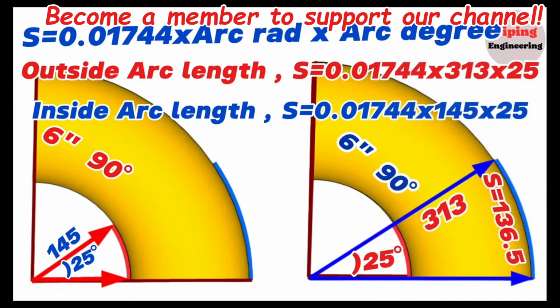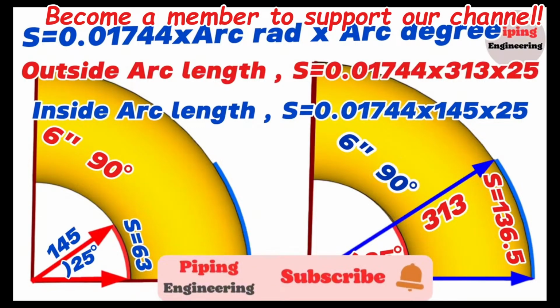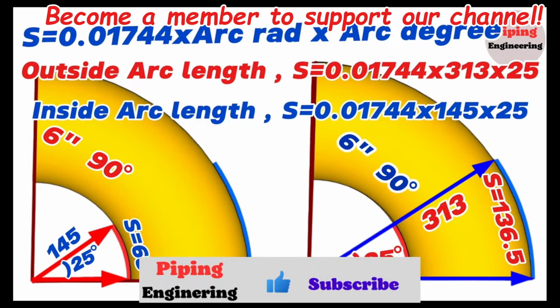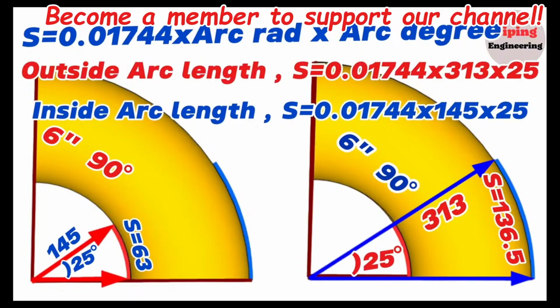So the length of the inside red color arc, S, will be equal to 63 millimeters. In fact, this calculation and marking should have been done on a piece of elbow. I have shown the inner and outer arc lengths of the elbow in two places so that it is easy to understand. Now we will delete one of the elbows and make the marking in one elbow.